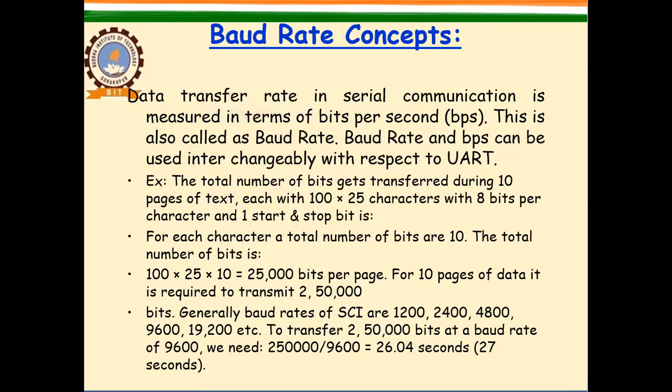The higher the baud rate, the faster the data transmission. So serial communication is measured in terms of bits per second, which is nothing but baud rate. So baud rate and BPS can be used interchangeably with respect to UART. Either we use baud rate or bits per second.